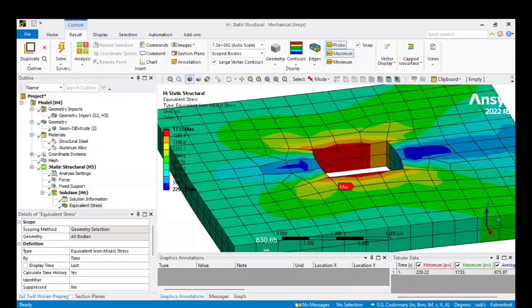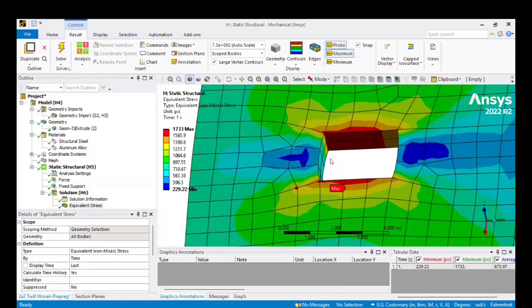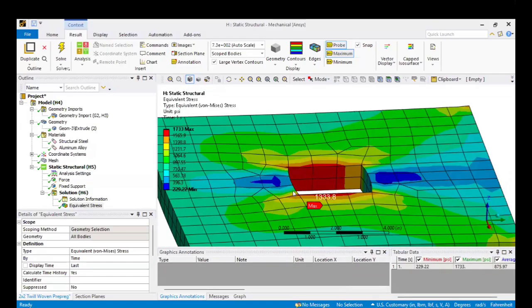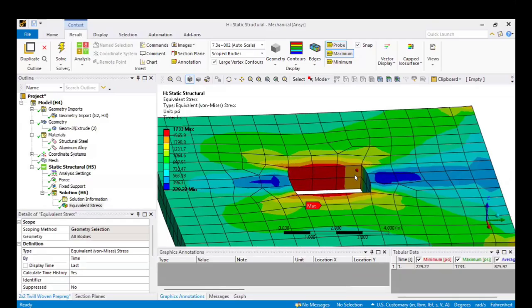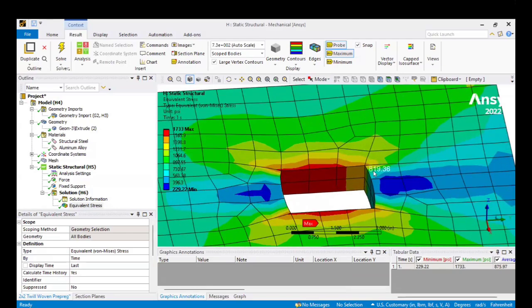So how do you think we should go about investigating the stress here? Are there any thoughts on what we can do to manipulate the mesh to look at these stress concentrations more? Because the mesh here right now is not too ideal. Any thoughts? You could make an extra fine mesh around that fold. Yeah, that's exactly it. Good shout.